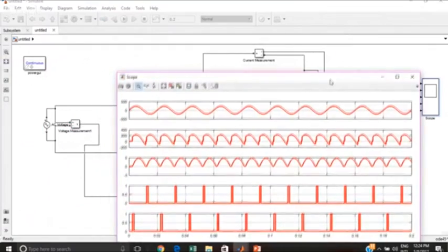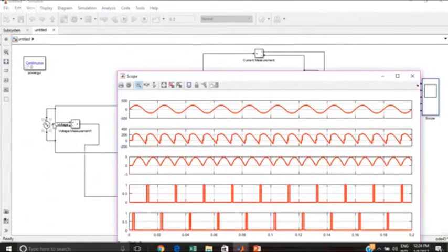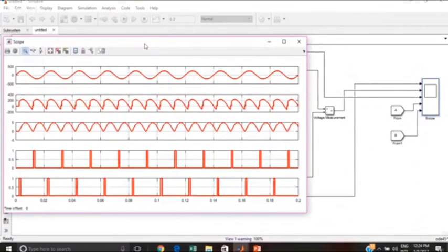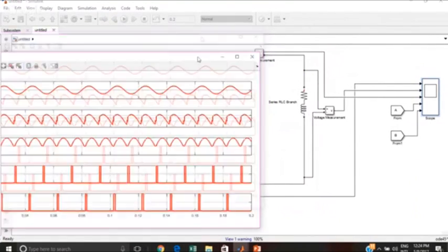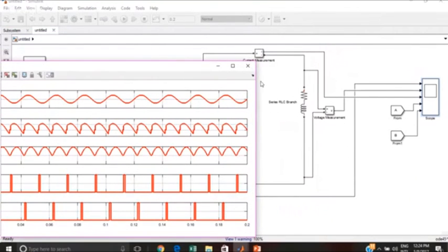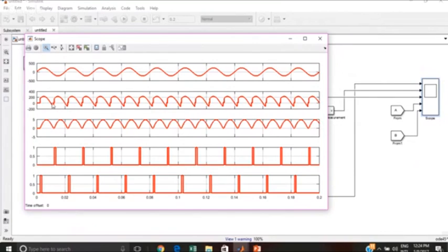So you can see the graph here. This AC supply was the supply, this AC voltage. Then this was the load voltage, which you saw in this voltmeter. Then you have a discontinuous current going here. That is this one, when the inductance value, the negative current is going, and sorry, negative power is there, in the sense the voltage is going negative, in the sense the energy that the inductor has stored is being given back and it is becoming zero. That's why the current is becoming zero.